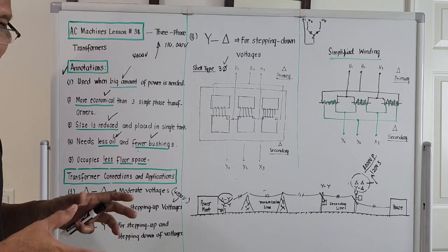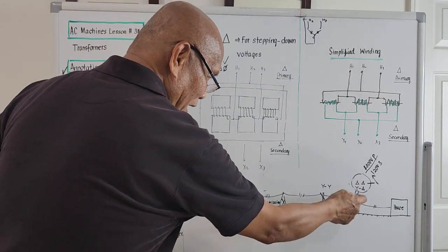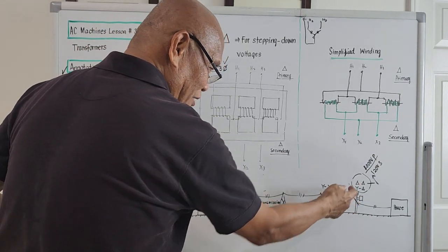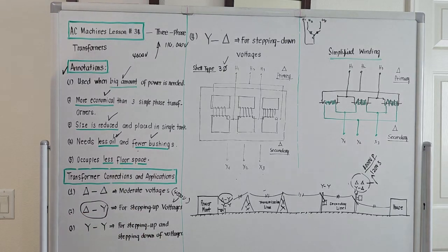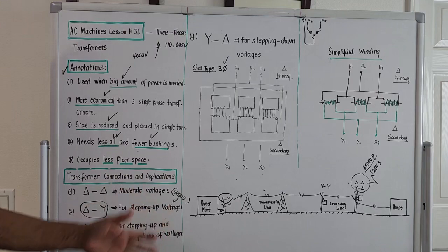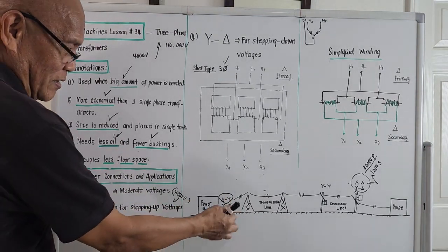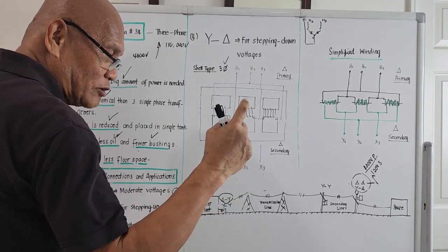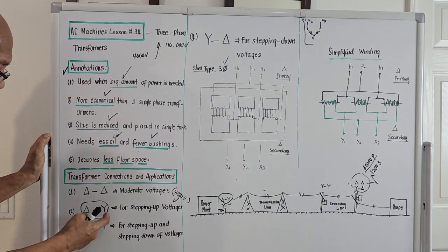If the voltage is too low to reach the distribution transformer near the houses, the power that will go to our houses is not enough. Instead of 120 maybe, it will go 90 volts. That's very bad. So it's a must that the initial voltage climbing this transmission line will be very high, and the transformer that is needed for that is with the connection delta to Y.